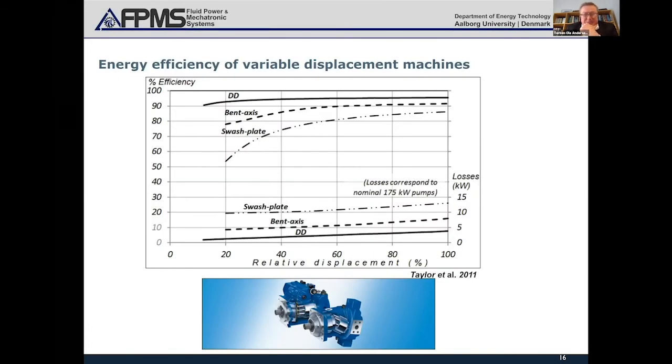Here we have why we are doing it, and it was actually introduced by a company, Artemis, in England first. And you see here the digital displacement units can have a very high efficiency over a relatively large area, where typically fluid power has an optimum somewhere, and then it degrades drastically when you have partial load. And you see that if you have an efficiency of 0.6, for example, and you have a transmission, of course, these efficiencies multiply. So 0.6 multiplied by 0.6, very, very low, very fast. So looking for every little chance to improve the efficiency is essential.